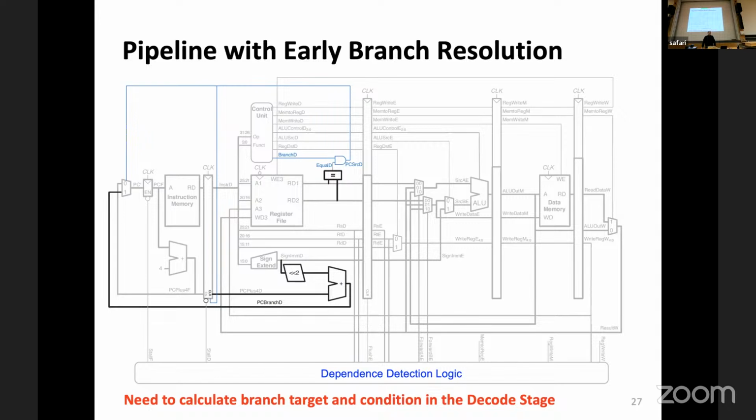So imagine your branch instruction. It has two source operands, and one of these source operands can be dependent, or both of them can be dependent, on previous instructions, right? You have the forwarding paths from the previous slides that give you up-to-date results for the execution stage. But you don't have forwarding paths so far for the decode stage. So in order to make it work completely, you also need to make forwarding paths to the decode stage. And we will see that quickly later.